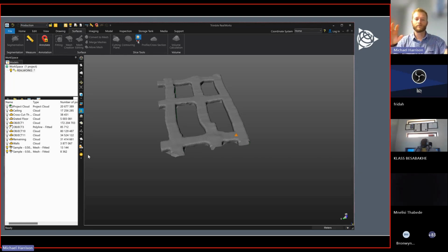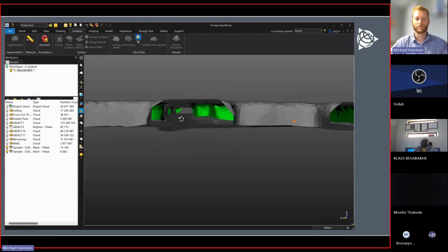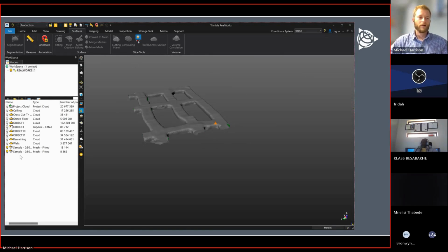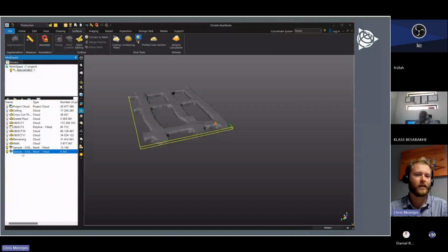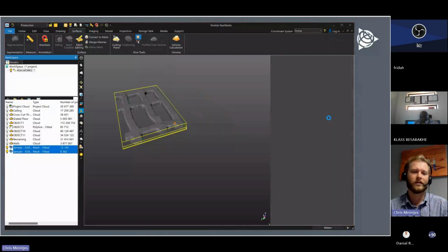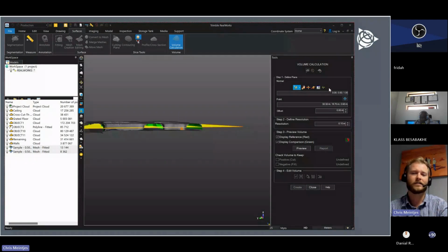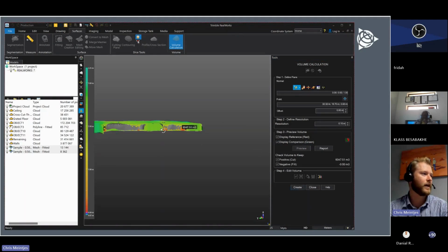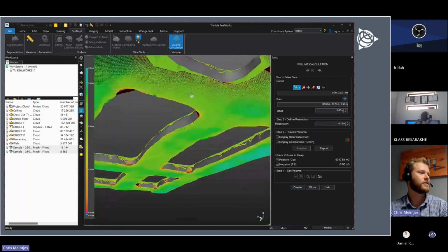In this method, I found that if you mesh everything first and then do a volume, which you'll see here. So here's our mesh. It's now gone from green to gray. So what I'm doing now is I'm selecting both of my meshes, the floor and the ceiling. And this can be done with any scan data, whether it's a terrestrial scan like a Trimble SX12, X7, X9, or a handheld SLAM scanner. Any point cloud data can be maneuvered like this, and you can see I selected the floor and then the roof meshes, and I ran.